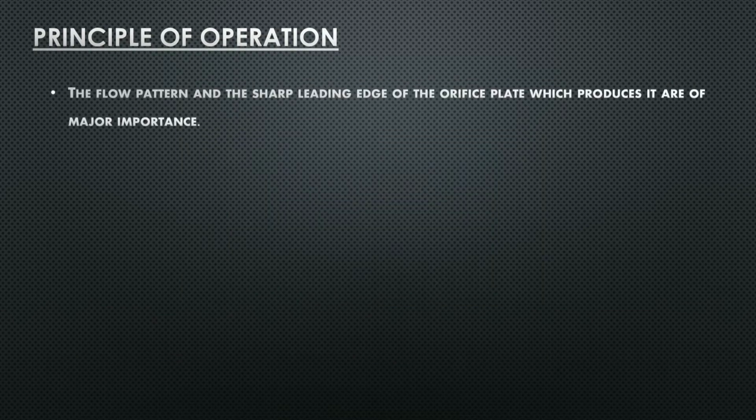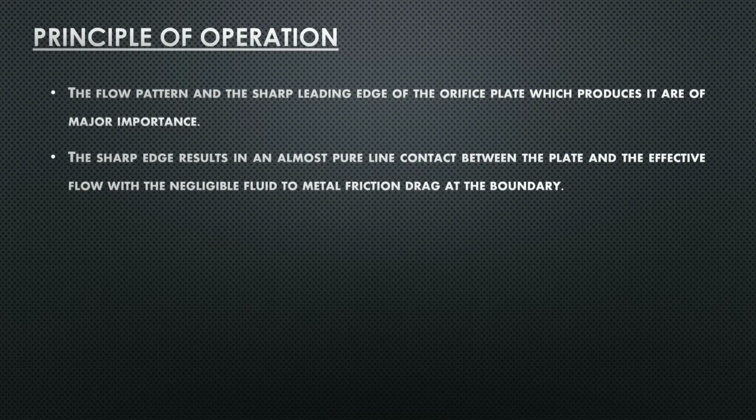The flow pattern and the sharp leading edge of the orifice plate which produces it are of major importance. The sharp edge results in an almost pure line contact between the plate and the effective flow, with negligible fluid to metal friction drag at the boundary.